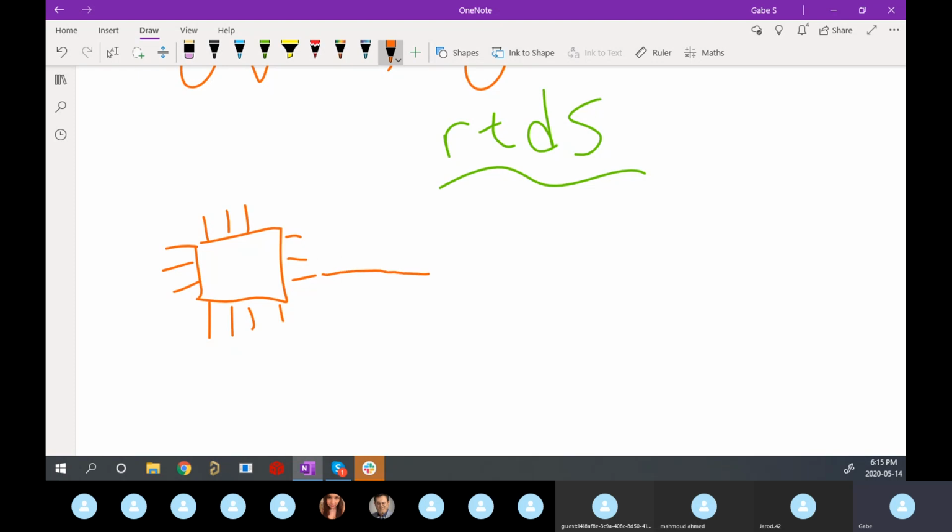So if this is a wire from the microcontroller, this guy here is a little switch, and then it goes to ground, right? So this is known as an active low signal. What that means is that normally you would think of on or active as being a 1, right? If I turn the light on, it's a 1. If I turn it off, it's a 0.